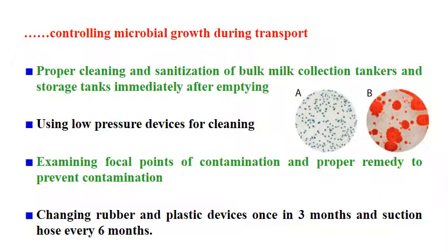This is in continuation of controlling microbial growth during transport: proper cleaning and sanitization of bulk milk collection tankers and storage tanks immediately after emptying. So this is very important. The collection tankers and the storage tanks should be cleaned and sanitized immediately after emptying. Use low pressure devices for cleaning, because high pressure devices may cause problems.